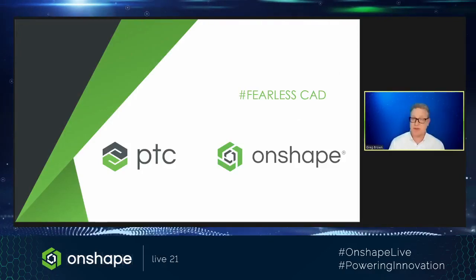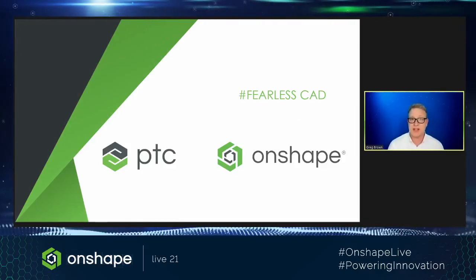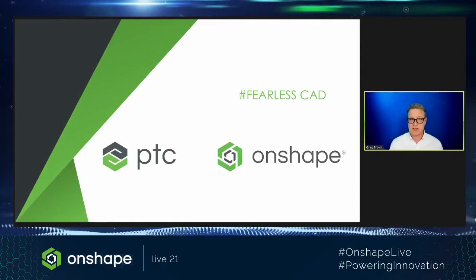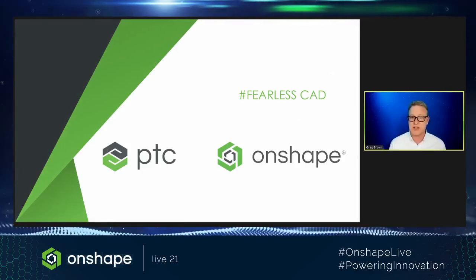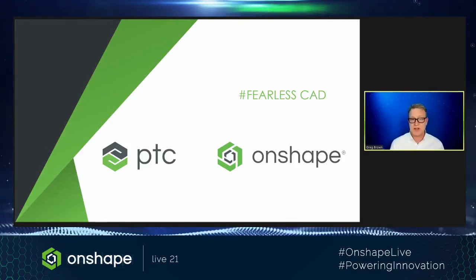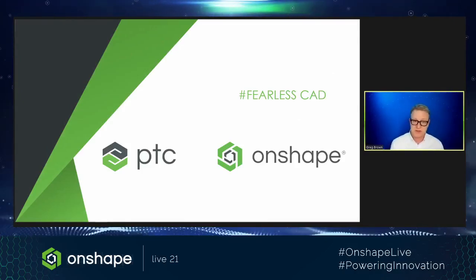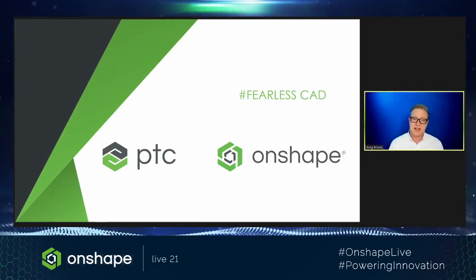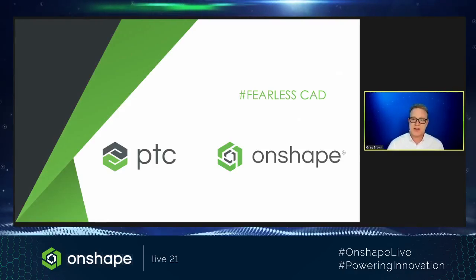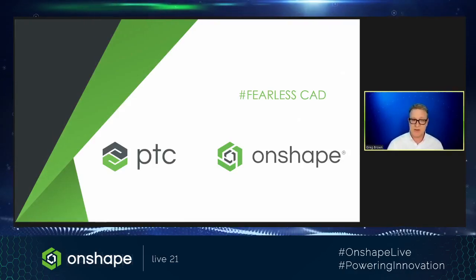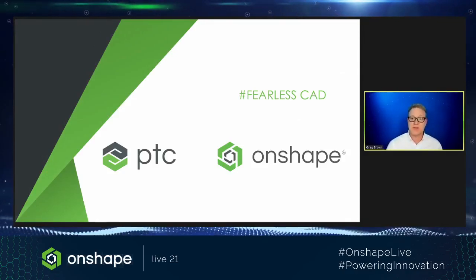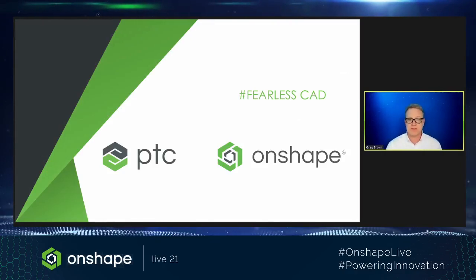Just remember another thing, there are also a lot of interesting and powerful tools. I mentioned one of them earlier on. It's in my Part Studio shortcut toolbar, which is a bridging curve. Bridging curves are really useful for creating boundaries, which you can then use with the fill surface tool. The fill surface was something else I showed during the demonstration as well. So those things tend to work together. So in addition to the ones at the beginning with loft and sweep and extrude, there are a number of other tools that you can find in there that help you build or repair surface models.